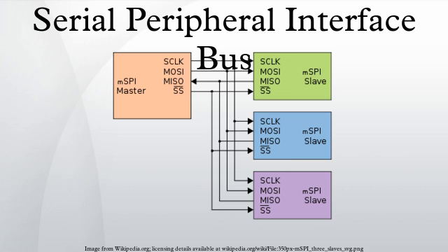Multiple slave devices are allowed with individual slave select lines. Sometimes SPI is called a 4-wire serial bus, contrasting with 3, 2, and 1-wire serial buses. SPI is often referred to as SSI, Synchronous Serial Interface. The MOSI-MISO convention requires that, on devices using the alternate names, SDI on the master be connected to SDO on the slave, and vice versa. Chip select polarity is rarely active high, although some notations suggest otherwise. Slave select is used instead of an addressing concept.